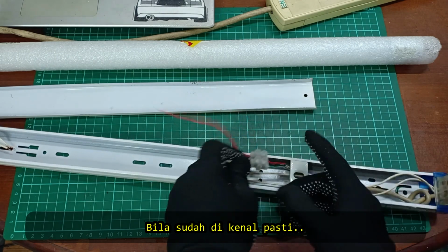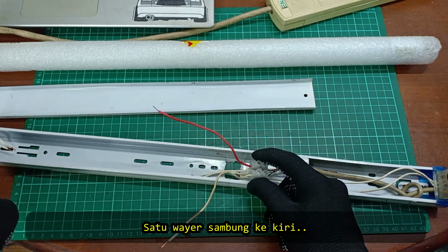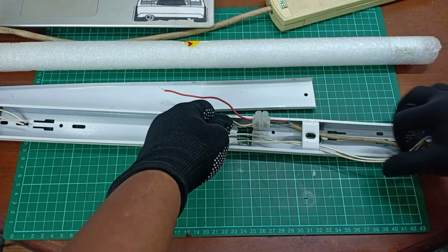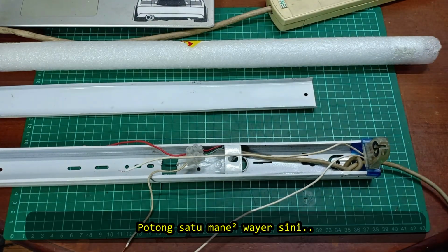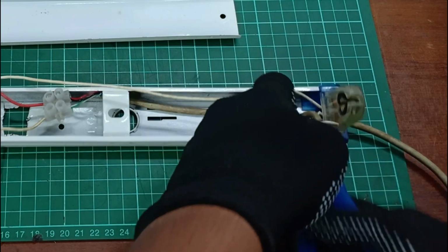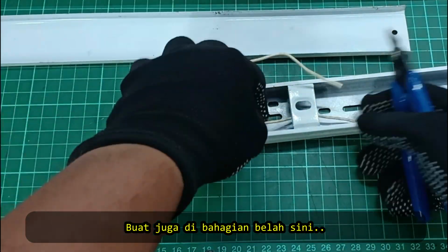Once you identify the hot wire, one of the wires will be connected to the left of the lamp. The neutral will be on the other side. Cut 1 wire here. We will use only 1 wire. Do the same with the other side.